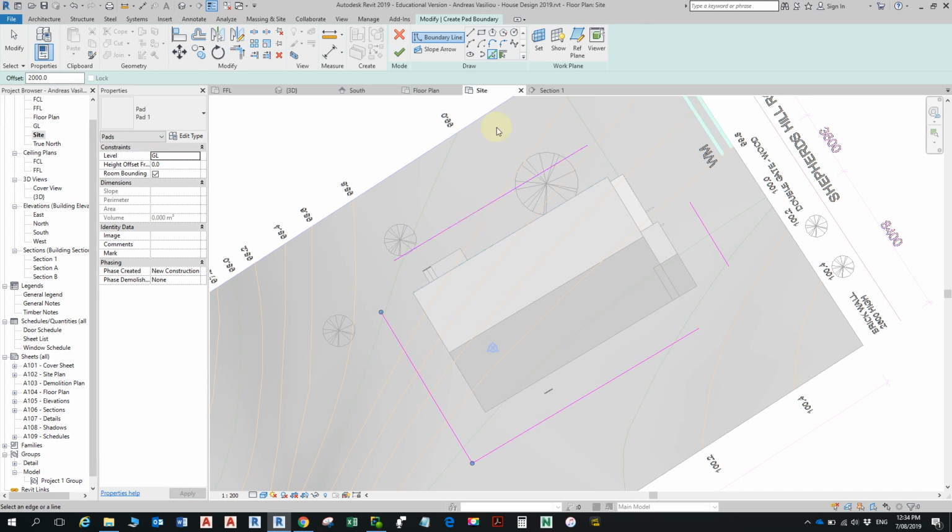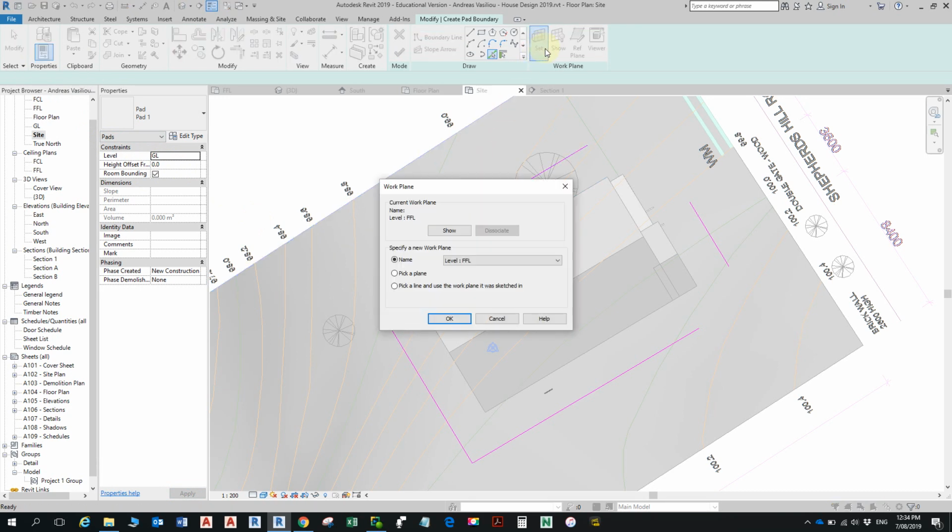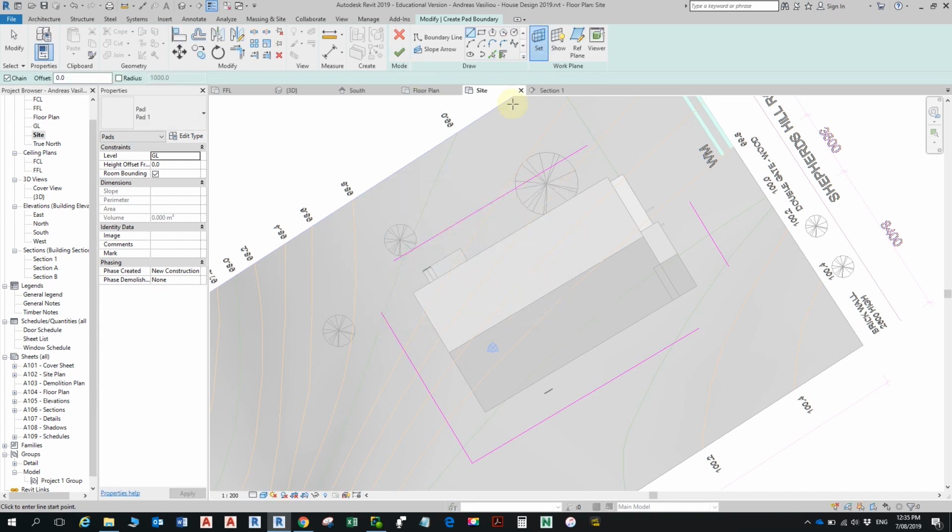Yes, I think that should work. The other way would have been to go here and actually, yeah, it's probably best to do that as well, just to make sure. Set that to GL as well, ground level. So everything is set to ground level, so we can't go wrong. Hopefully, just checking everything. So now I've got that. I can just go to here and trim extend and just do that.